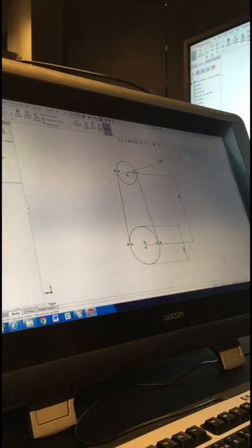Okay. So what's going on here? I'll just grab that for you. So that's coincident. So the end point of the line is on the circle. That's tangent. The line is tangent with the circle. You need to have that one also tangent and that one also coincident. So select the circle, hold Control, select the line, tangent. Circle, end point of the line, coincident.